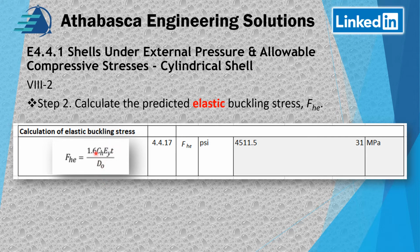And then of course we figured out in the previous preamble step the CH, based upon the shape and the dimensions of the object. And then basically we calculate our elastic buckling strength to be, it's quite high, 4,500 PSI. And there's the metric version right there.